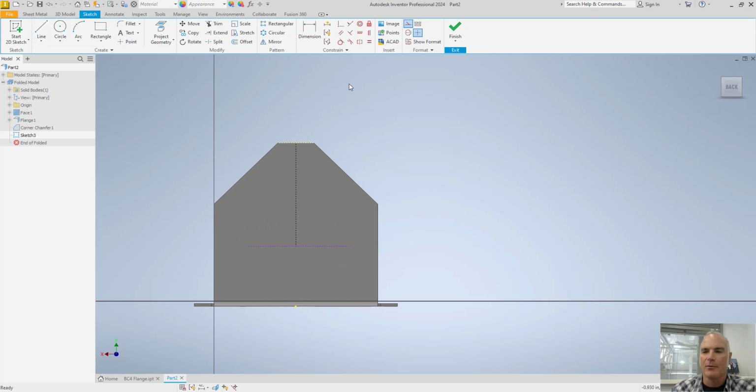So how does this help? Well, by coming in here and putting in a few constraints, like the midpoint of that needs to be at the endpoint there, these two endpoints are always going to be exactly the same distance apart. So when I come back in here to put my points in for my holes, I can say there's 1, there's 2, there's 3, there's 4. I don't need to put in any more constraints because they're already constrained to those lines.